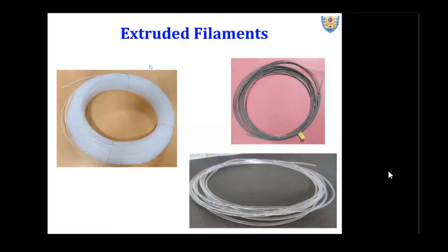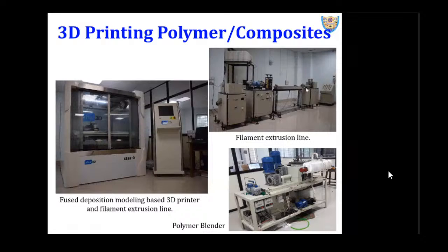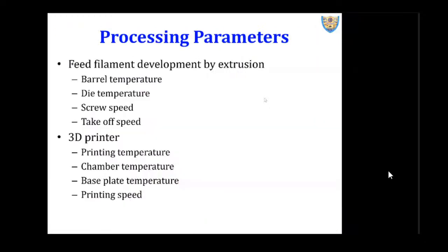What do you mean by vented or non-vented type? Vented types are those wherein we have a specific vent to take out the flue gases which get generated in the barrel of your extruder. And if you have a vented type, you can take out all those gases, and what you will see here is the filament cross section without any pockets. That is fine, but I don't have that vented type. So I said, yes, this is what I can produce with my existing system.